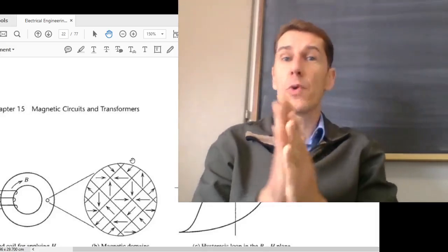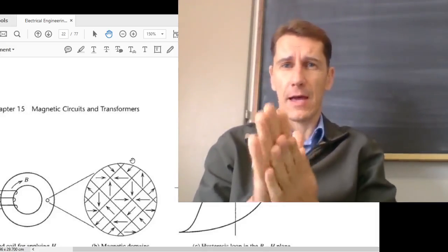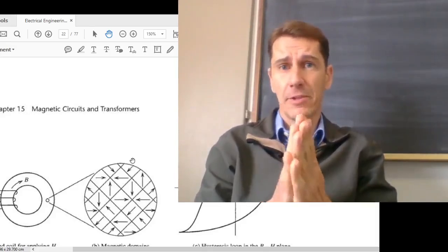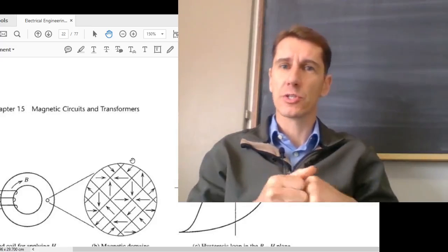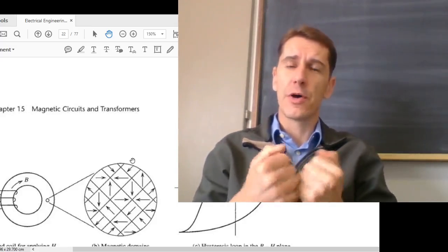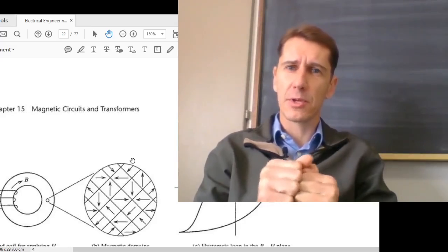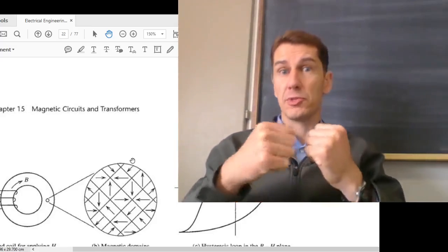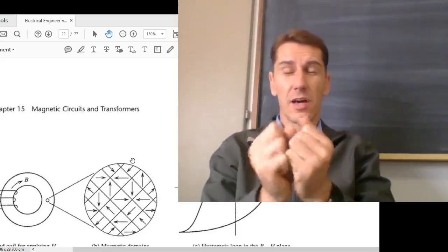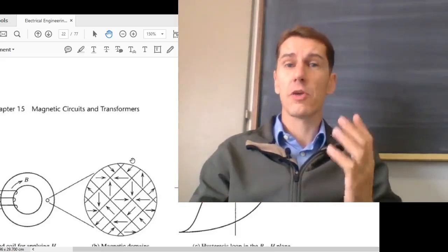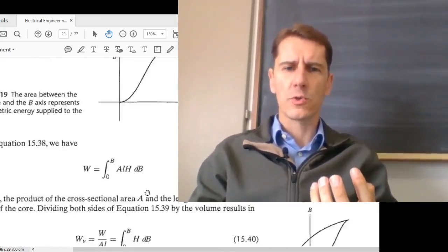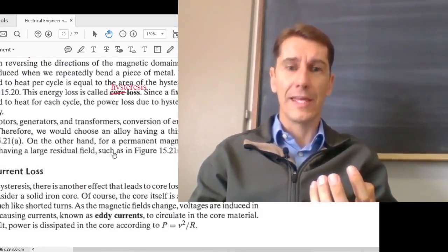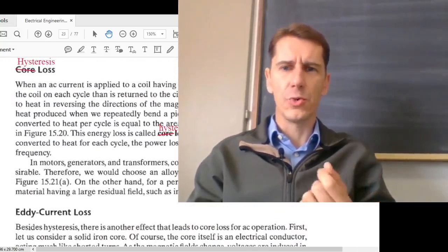Now what happens if you rub your hands together? You get heat, and the same happens in this hysteresis loss. Physically, with those atoms rubbing against each other, because they have to go left, right, some of them turn clockwise, others counterclockwise, either way, you've got a lot of rubbing happening inside of that core. So that causes what we call heat, or what we call hysteresis loss.